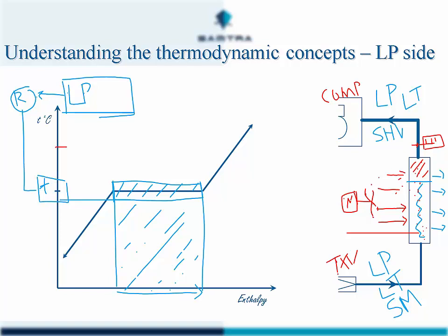So if everything's working correctly, if the temperature is warmer, we go up, and we can then come across and we can plot exactly the temperature on the temperature enthalpy chart, and that will be giving an indication of the superheat value. And the superheat is allowing us to remove a little bit more heat energy from our refrigeration system. So that is the application of using our pressure gauges and a temperature sensor to measure the pressures and the temperatures of the system.